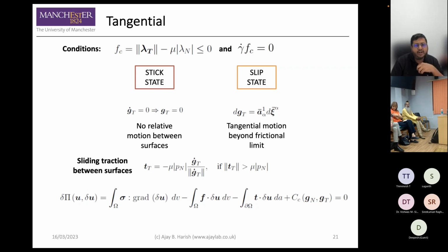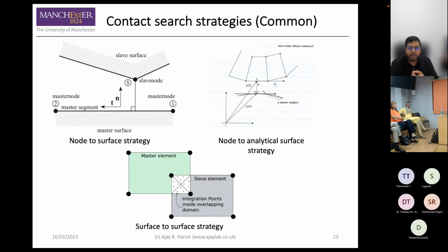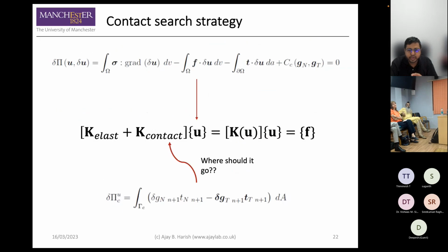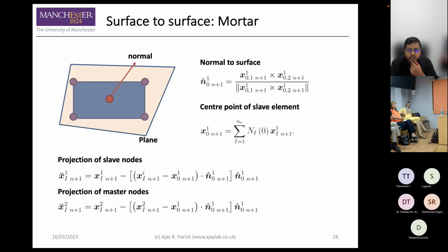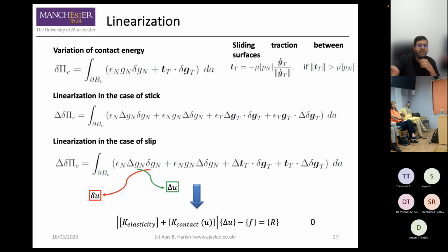Yeah, we can consider them with the model with the stick state and the slip state. The only thing that becomes complicated is when we put it into the next formulation here. In the linearization for a stick state and a slip state, we would have another term that comes in because of the change in the friction coefficient.